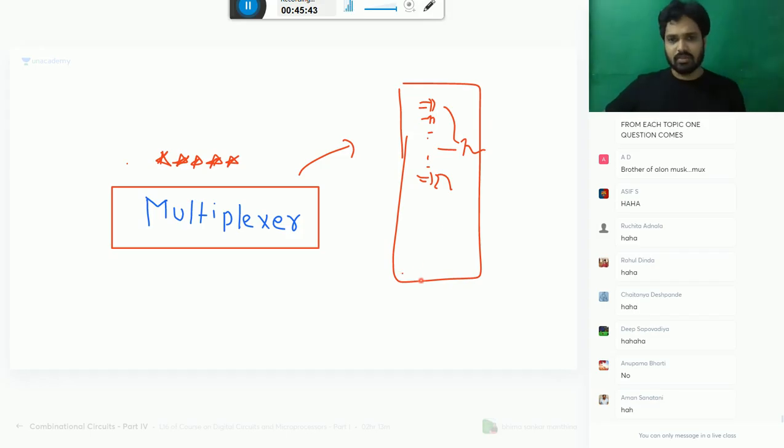Assume you take some discrete gates and connect with some wires. You have wound wires and made these gates like this. Connections are made with the hand. What is the disadvantage? Different wires will have different lengths. They may give you different propagation delays. One simple answer.